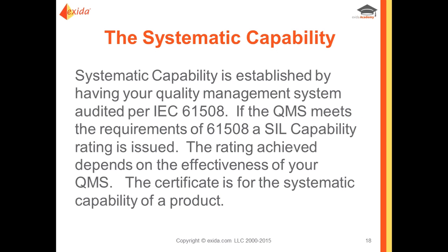To be compliant, you have to be in this tiny triangle in the middle of all 3 of these circles. You have to be compliant in the SIL capability and in the architectural constraints and in the probability of failure. You cannot just meet 1 or 2 of these and say you're compliant. You have to be in that sweet spot and meet all 3 of these to actually have compliance and be that SIL that you're talking about.